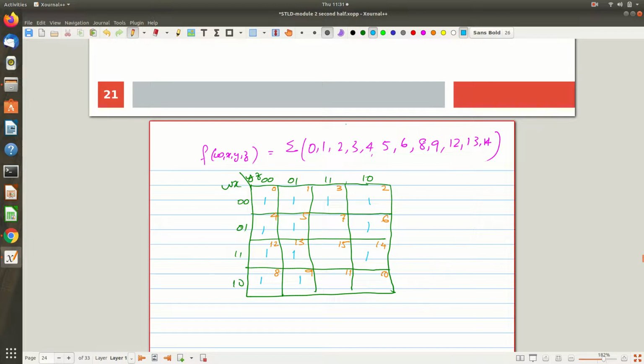Now I want to find out the largest grouping of ones. So here you can see it's a very nice grouping, right? Once you get this grouping, that's all. If you miss the largest group and wrongly make the group, you may get the wrong answer. So always go with this structure. Some kind of rectangular shape you will get, with the largest number of ones.